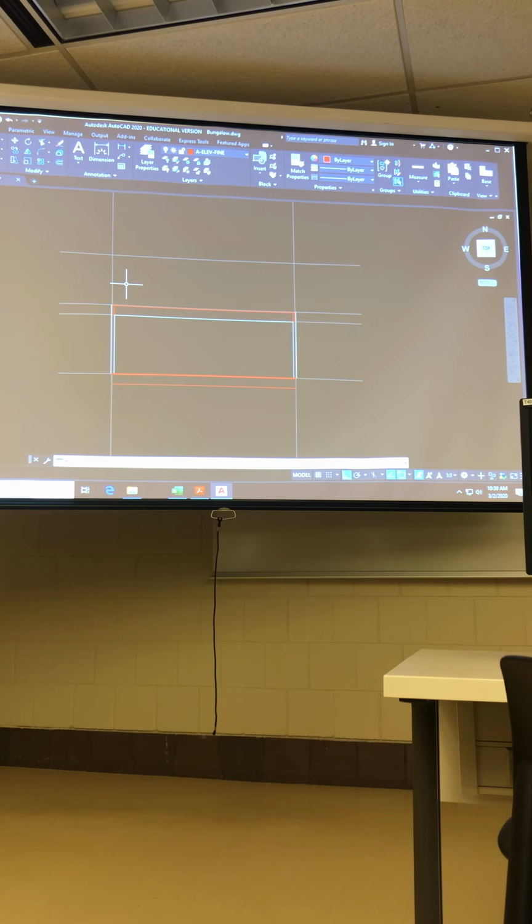Because if I think about it that way, what I can do is go back to my drawing, and this construction line that I started with initially, I'm gonna draw a vertical line. That's the central line of my room on the upper level, the center line of the house too, by the way. And I'm going to offset that line 7 feet in each direction. And I'll only actually do it in one direction, because I'm gonna mirror the truss again. So that's the face of that web member, face of the wall in the bedroom. And I want to offset that 5.5 inches to the outside because my web members are all 2x6s again.